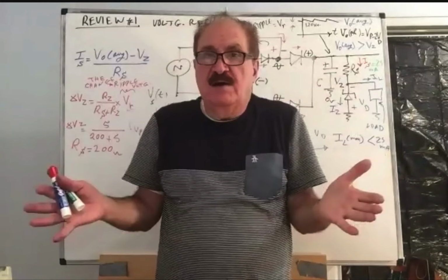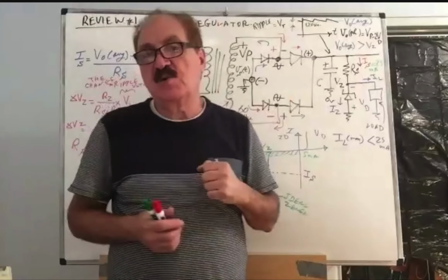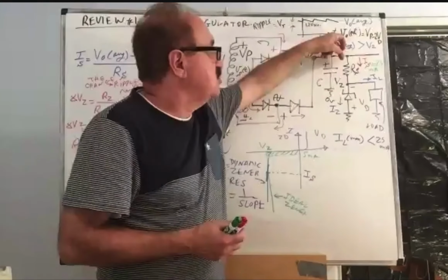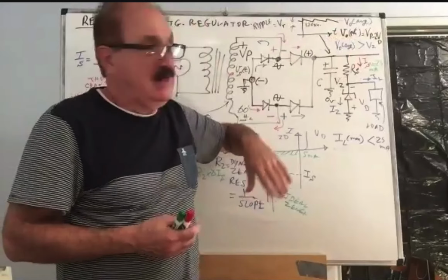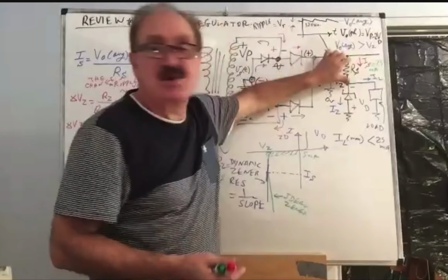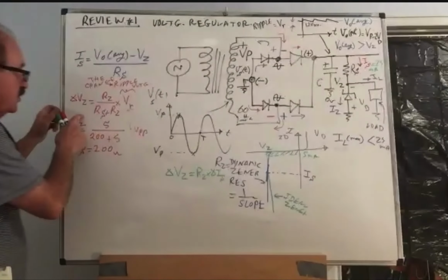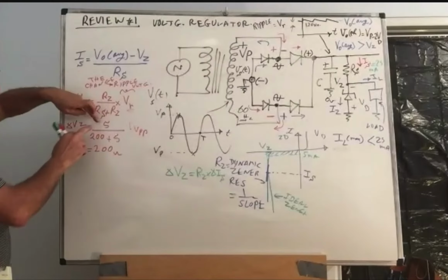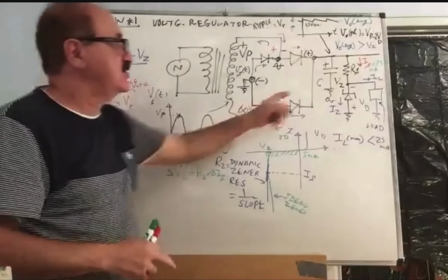But you cannot do that with one single Zener. Unless you know what you do, you make this current 125 milliamp, for example. Well, if you did, you make this current 125, then you've got to reduce RS. But if you reduce RS, this is what will happen here. If you reduce this resistance, then your ripple will increase on the Zener path.